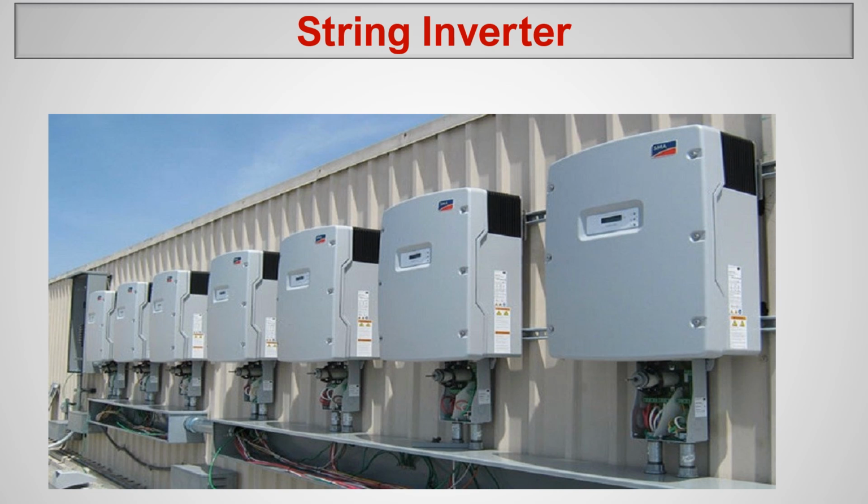There's no meaning of string inverter because you have only one series-connected set of panels. But when you go for a higher size, like a 20 kilowatt system, we will probably have two or three strings. This is based on how your consultant or solar company designs the panels.